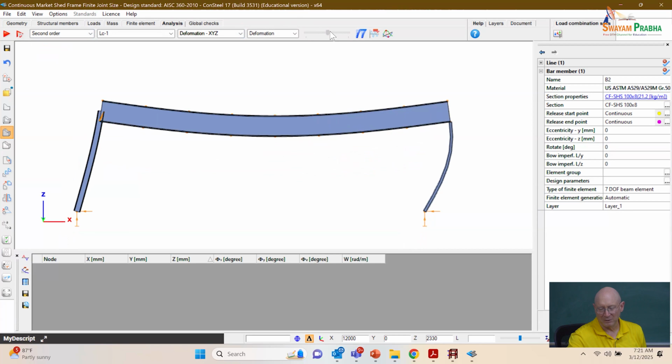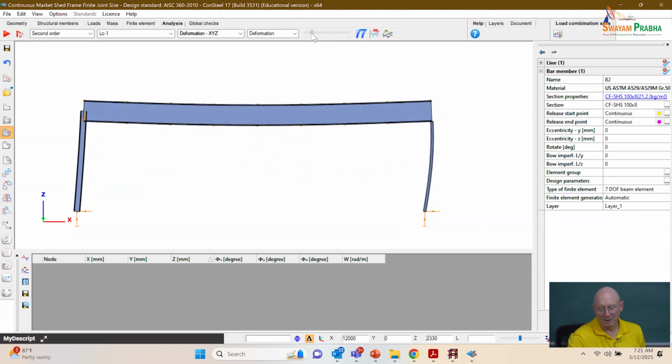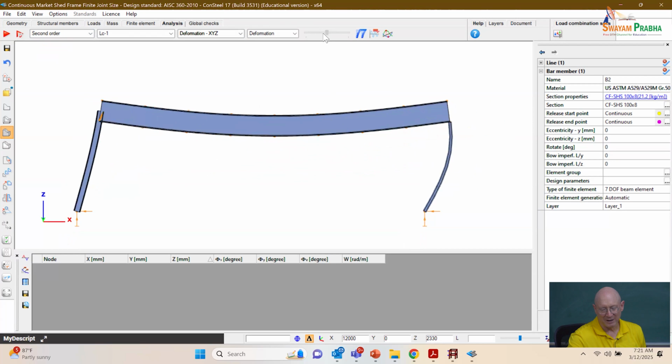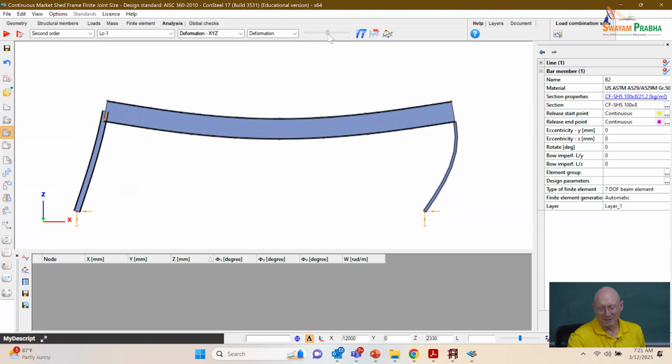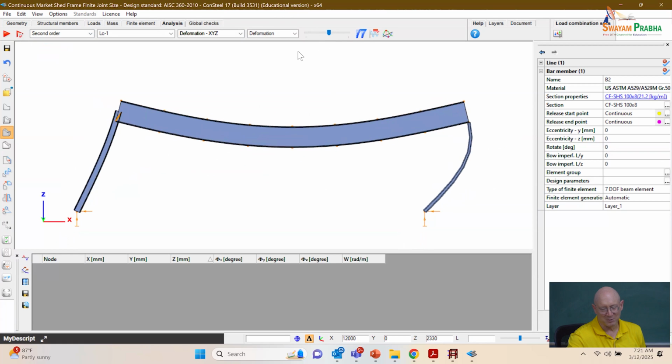And so if we look at the deflections here, that HSS section is kind of getting beat up by the frame a bit, right? It needs to bend with the major axis bending rotation at the end of the roof girder. So it's bending way out there.